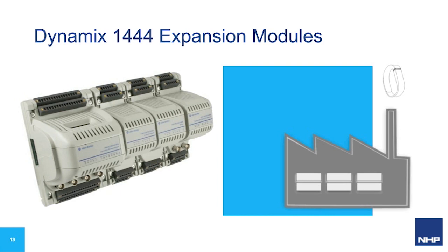So what's important to note here, though, is when we move to an integrated condition monitoring system, we don't need the tacho system. We can actually pass through the speed value that is somewhere in our control system. It can be whatever speed you're referring to, a variable or whatever you need for that specific measurement. We can pass it through to this module so that it can use it in its calculation.